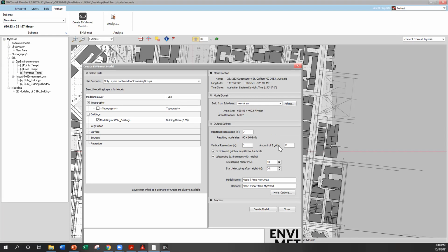We are just leaving the space to facilitate the wind circulation, that kind of thing. So that doesn't need to be analyzed in much detail. That is why we start the telescoping after the height of the highest building, just to make the simulation faster without losing a lot of details. The height of the telescoping should be at least 3 times the height.